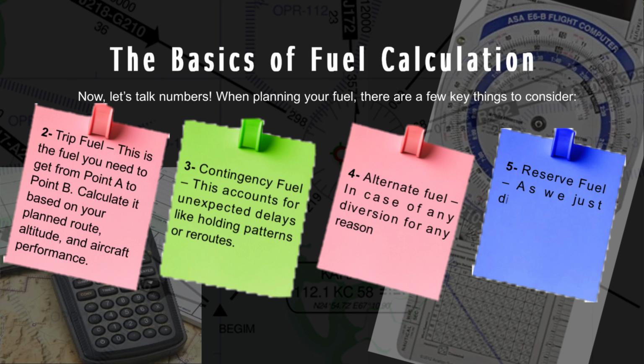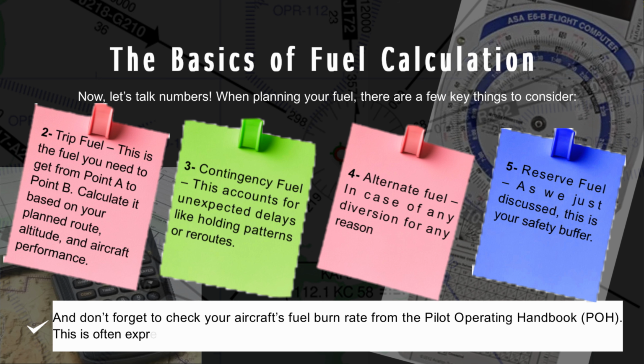5. Final reserve fuel. Minimum required fuel to ensure the aircraft can remain airborne for a set duration, e.g. 30 minutes of holding at 1,500 feet above the alternate airport. This is a mandatory safety reserve. Extra fuel, discretionary. Additional fuel decided by the captain or operator based on anticipated conditions such as poor weather, expected holding patterns, or operational needs.